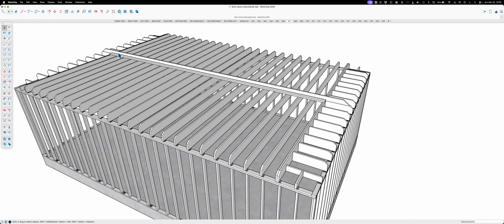Then you come back with your standing. This is the one that actually keeps the ceiling flat, is the standing one. And what we used to do would be a horizontal nail in the bay, in between the joists, and then an angled one down into the joist. So you'd go horizontal, angle, horizontal, angle, horizontal, and don't walk backwards when you do it. Do it walking forward, because you can walk backwards right off the building. You don't want to do that. Saw a guy fall down an open fireplace doing that when he was rolling black felt paper.